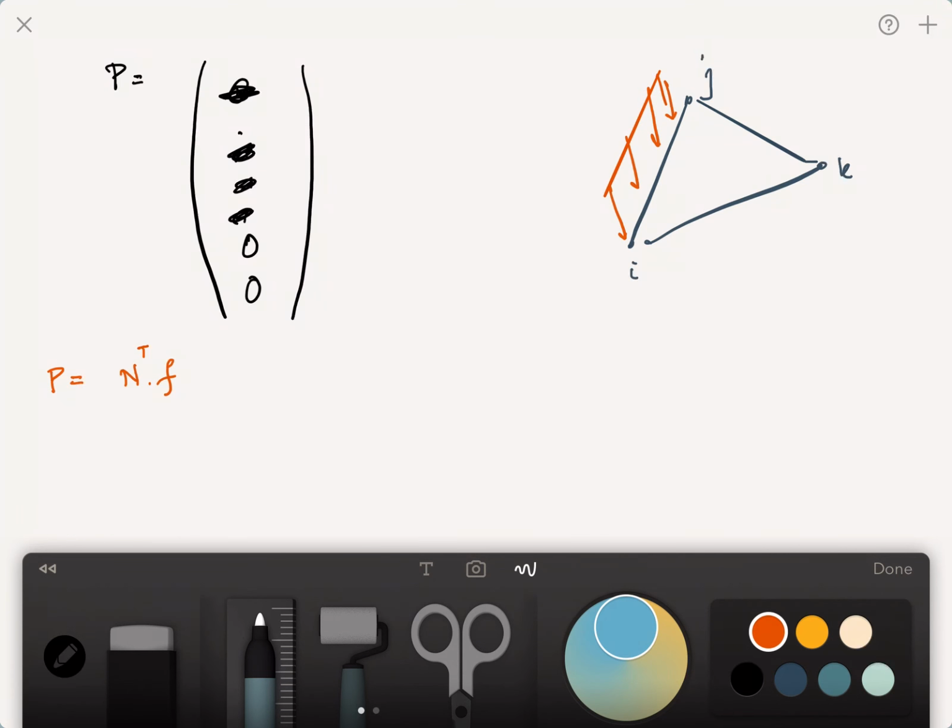So as a rule, as we have done before, if you want to find the load on an element in which you are doing some kind of transformations, also with the coordinate system, and if you have loads, then you must always multiply them with the shape functions. These shape functions are much better suited when you have distributed load acting across edges.